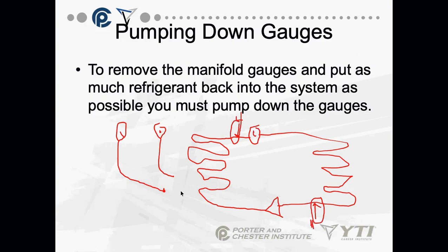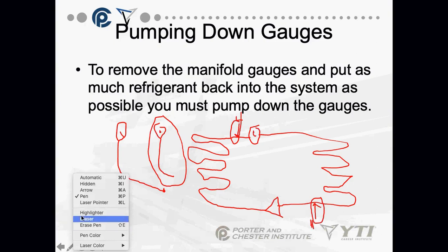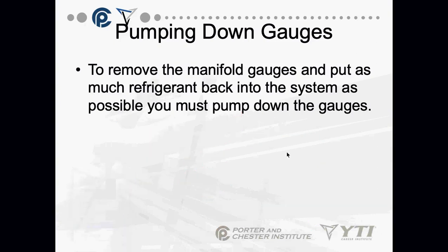So as I go through this, even though I don't have a set of gauges in my hand like I would normally like to have, I just want everybody to understand my goal is that I want to lose as little liquid through my gauges as humanly possible. That is my whole goal of this thing, lose as little liquid.